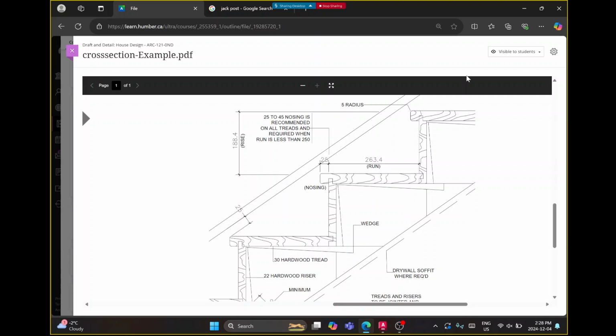And with stairs, by the way, if they're in a residence, you'll almost always find they're made out of wood. And if they're made out of wood, it's going to be hardwood. So it's not going to be any type of plywood or layers of veneers, because the idea is that as you walk up and down these stairs, they'll eventually wear down. To refinish it, if you call somebody in, they're just going to sand off the top 2-3 millimeters, make it nice and smooth again, re-lacquer it, paint it, whatever you had, and life goes on.